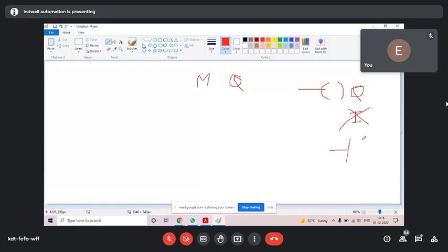But in contact, in NO and NC, you can use any bit address. Remember from now, always remember: in coil, we can use only output address, but in contact, we can use any bit address. And what are the addresses in bit?